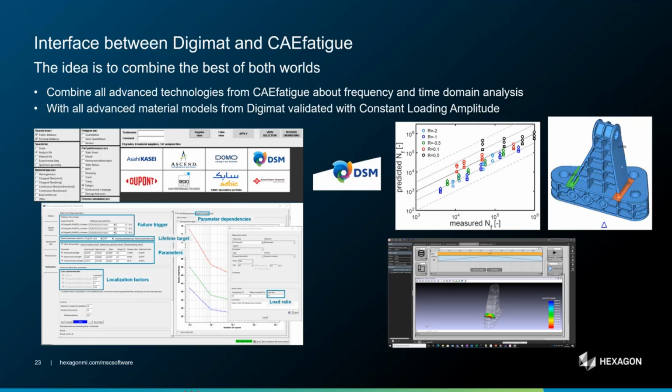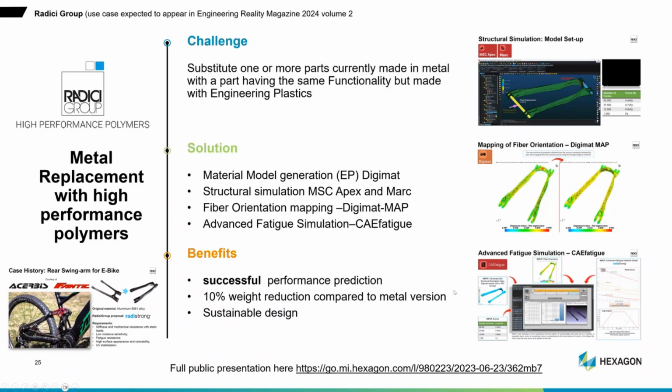It's stored. And CAEfatigue leverages this information, and Digimat leverages that information to create fatigue curves on the fly that are relevant element by element. There would be a different instance of the fatigue curve that we're going to be picking for calculating the fatigue life. Okay, this is fully integrated and available in CAEfatigue, both in the time and in the frequency domain.